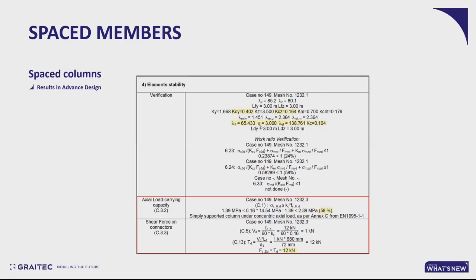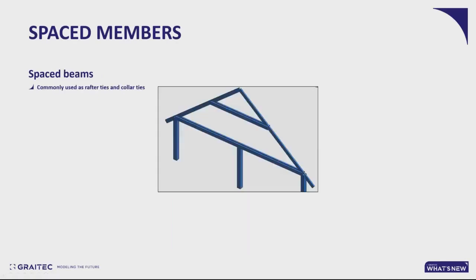And also we've got the connector types, which in turn give us an effective slenderness and a very small buckling coefficient that is actually driving the design and giving us the utilization for the actual load carrying capacity verification. And then we've got the shear force to properly design the connectors, with the distribution formula being the one for the two-shaft configuration.